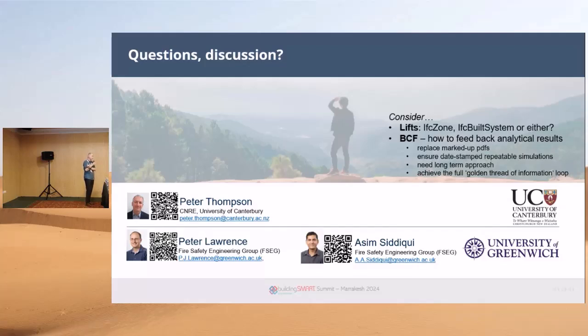The expanded IDS is really that in those final stages of the design loop, passing on to the authorities, we took it the extra stage to also add in elements of the outcomes of the simulations into the IFC file, our custom property sets, to express the outcomes in the IFC file for regulatory review, and then check that those data points were in there. I called it an expanded IDS file. Okay, I understand. Basically to cover the extra data for those simulation routes. Yes, thank you.